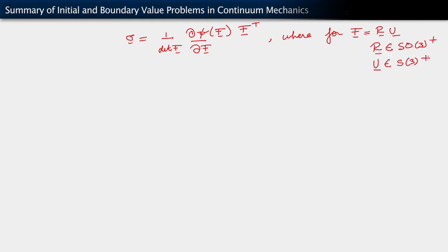For these conditions, we also have that psi of F has to be a function of F only through the right stretch tensor. Okay, so that is our condition of frame invariance. All right, so this is the situation that we have for solids.